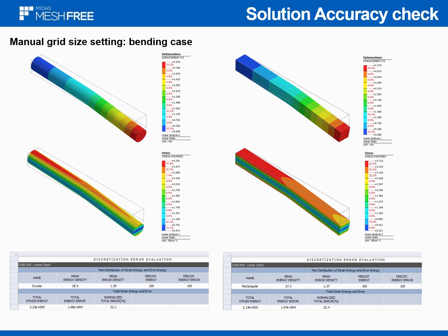If we do the same example for the bending case, the situation looks much worse. So definitely using the size 1 by 1 by 1 in terms of stress is not acceptable for both of the cases. We can use it only for simple elongation stress and with proper boundary conditions.